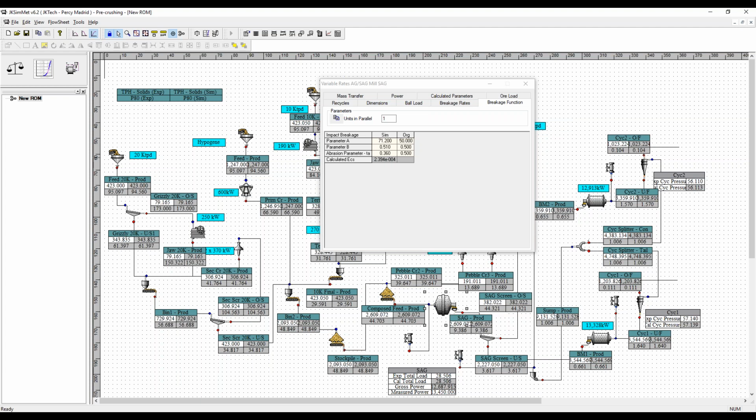It's not just software training. We go through all the fundamentals on comminution, all concepts, so that helps attendees to better understand the models, the comminution principles, also the approach of each particular model. We cover from ore characterization, the actual model structures and their limitations.